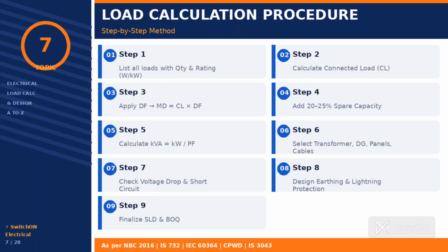Then suppose you get 580 kVA, but standard transformer is not available with that value, so you have to go for the next higher size. So the next transformer size is 625 kVA. Your result is 580 kVA, but you don't get that 580 kVA as a standard transformer with any manufacturers. So you will go with a 625 kVA transformer.